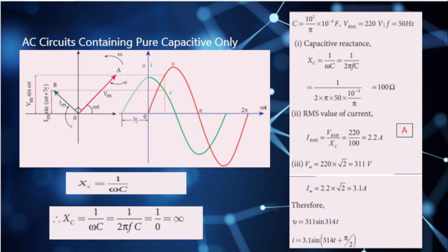Now, one final thing that I have not mentioned in a purely capacitive AC circuit is capacitive reactance, which is this XC that we have here, and you'll see over here on the right as well. Capacitive reactance is the resistance offered by the capacitor, and it's also measured in ohms. Capacitive reactance varies inversely with the frequency. So again, we have something that is basically the inverse of what we stated for a purely inductive circuit.